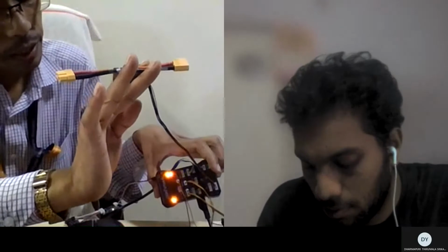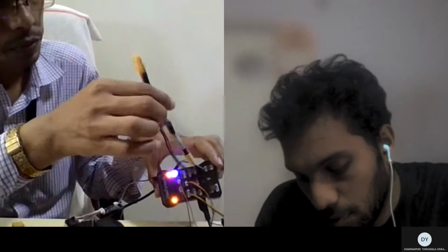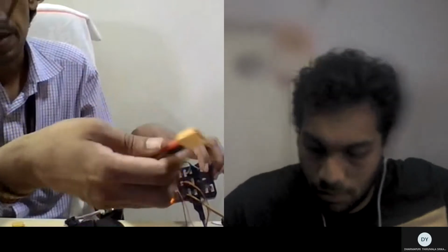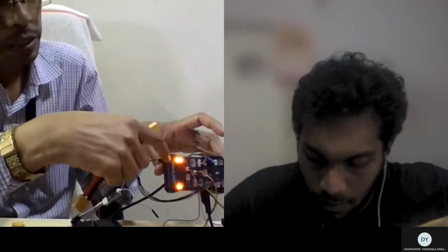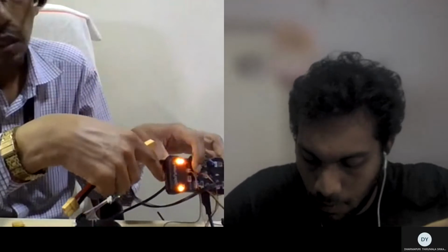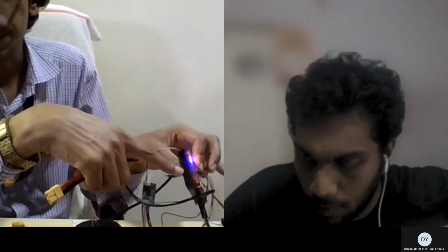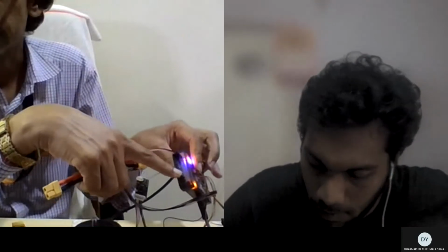You can go with the circuit diagram. I will go through one website where you will see these diagrams also. So the power module will be connected here, and the power module will be connected with the battery. Through the battery, this powers the flight controller. But sometimes this is not going to power the rail where your pins are. So this has to be powered again.